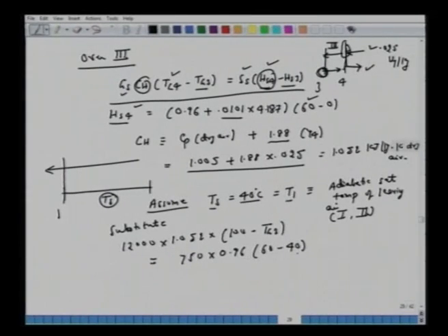All right, this is what we are doing, 60 minus 40. So 60 is the leaving temperature of the solid, and we have assumed 40 degrees centigrade, and the solid remains at this temperature throughout. From the region right here, this temperature is constant at Ts, so minus 40. So from this one can get Tg3. If you calculate, Tg3 is 99 degrees centigrade.